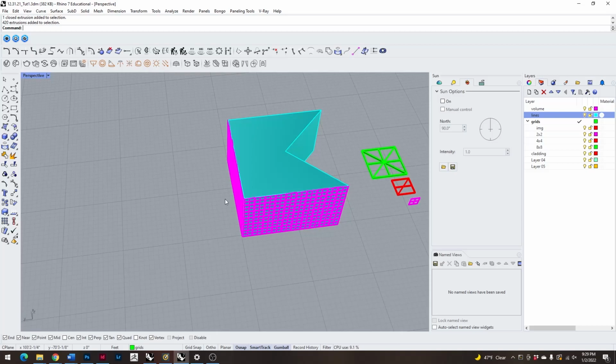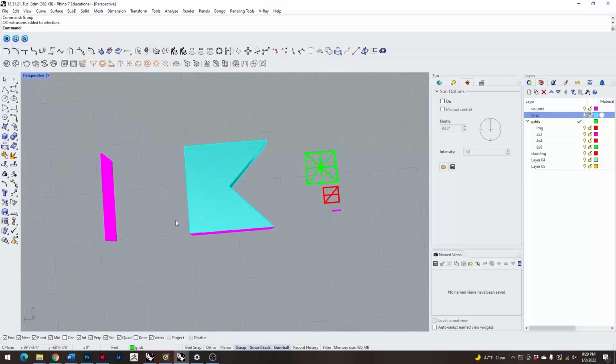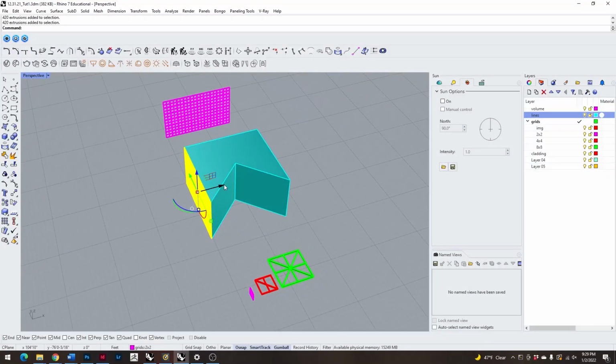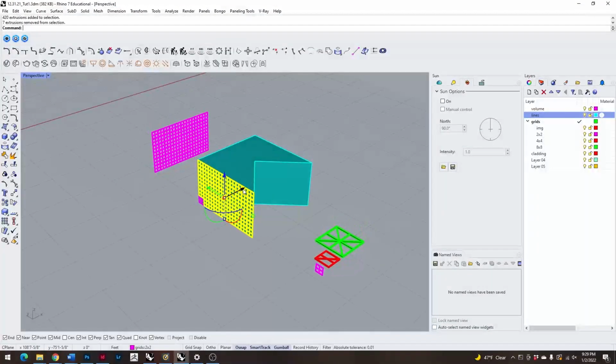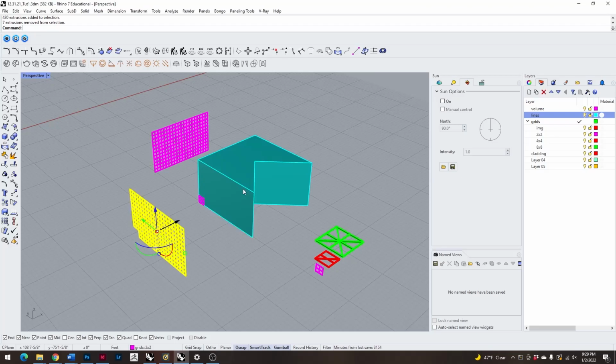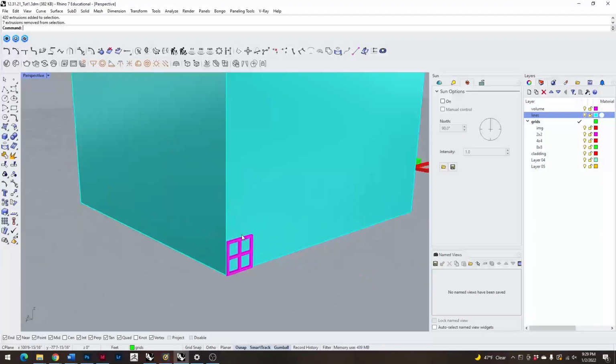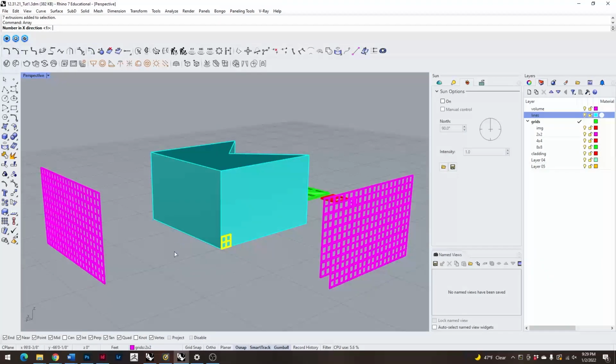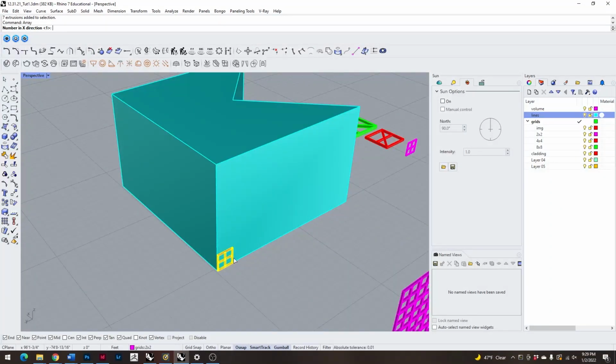Another way to do this, I think, I'm going to move this off by a known dimension so that I can later bring it right back and group it so I don't have to worry about highlighting everything at the same time. I'm going to deselect that one. I'm going to move this -20 feet again. Another way of doing this would be the array command, where having this selected and typing in array, we could say, well, I want approximately 10 in the x direction.